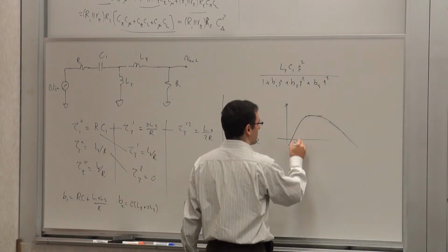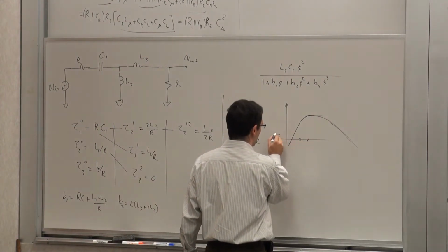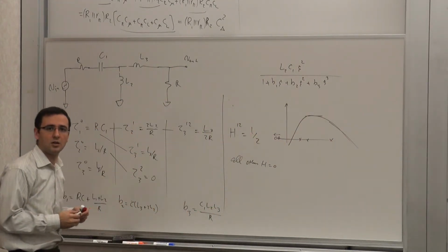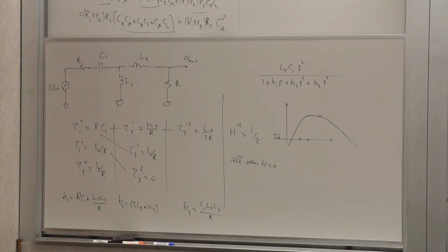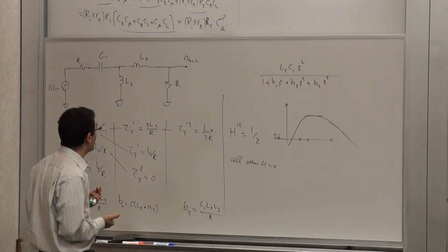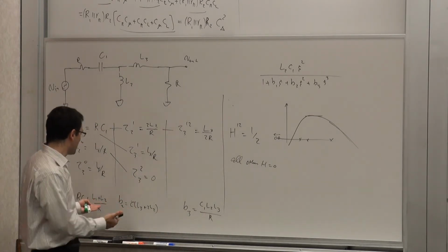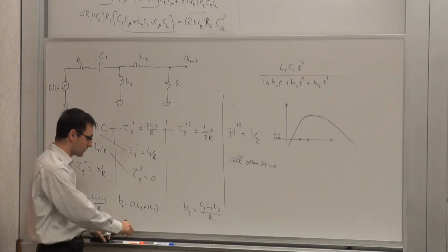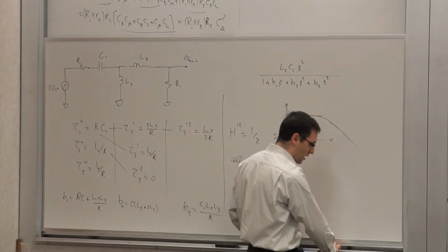So you got a couple of poles here, you got 2 zeros at infinity, and then another pole. You can think about them as 2 inverse poles and 1 regular pole. It's a bandpass system. And if you wanted to design it, because now you know what the coefficients are, you can play with them. You can actually know what affects what. So it helps you with the design of this thing.